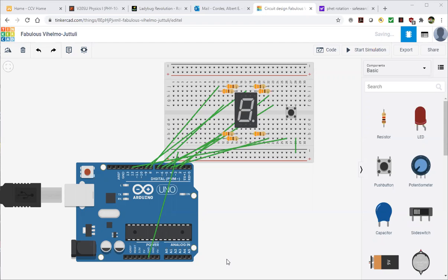Okay, so you have to use this particular column. So that means pin number 1, which is this one in the upper left-hand corner, goes to segment A. They're calling it cathode A. This one goes to F. This one is the common anode. 4 and 5, there's no pin there at all. This is the decimal point. We won't be using that. EF, no connection. CG, no pin. B, and then also another common anode. You can use either of these two, doesn't matter.